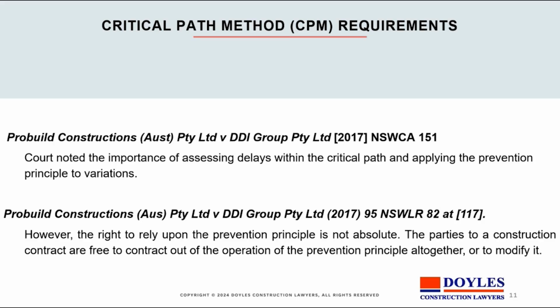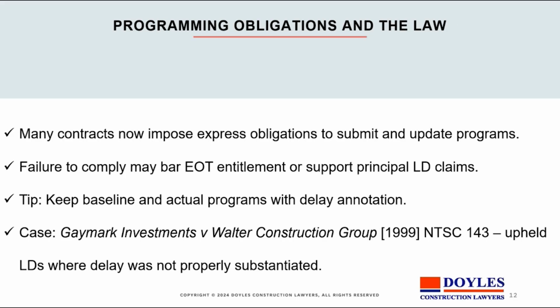So you've got to look at the programming obligations under your contract. Many contracts now impose express obligations to submit an update program. And it's important that you get a workable scheme for doing that, because with a few complications, otherwise the program becomes hard to submit, hard to present sensibly, and can cause problems for the person who wants the extension of time. So a contractor puts in extensions of time.